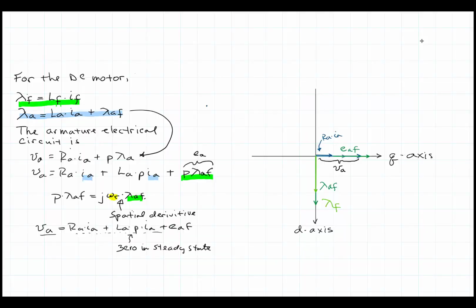Now, I'd like to point out something very interesting. I'm cleaning up this circuit a little bit. What we have is this DC motor. Let's look at it from a little different perspective. This is the description of everything that's happening on the armature winding. It's lined up with this axis that we're calling a q-axis, and that q-axis is representing the main torque production of the machine.